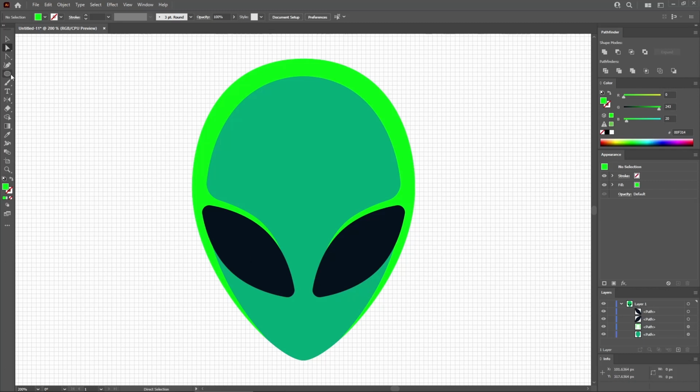You'll need again the ellipse tool, so select it from your toolbar. Click again on your artboard and let's create a 5 by 15 pixels shape. Use again the eyedropper tool to fill this ellipse with this dark color. Use the selection tool to align this tiny shape with the bottom edge of the head. Let's drag it 45 pixels up. Move it in this exact position.